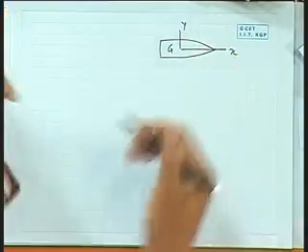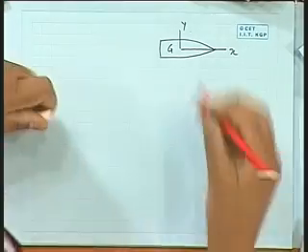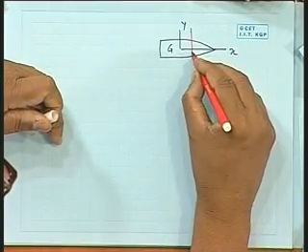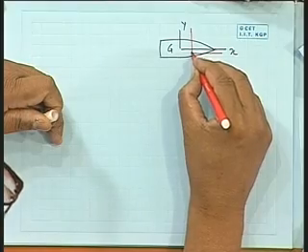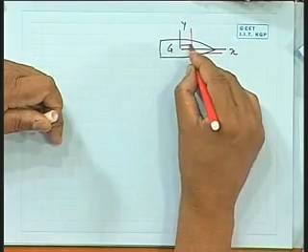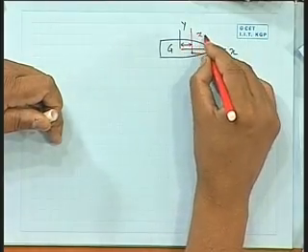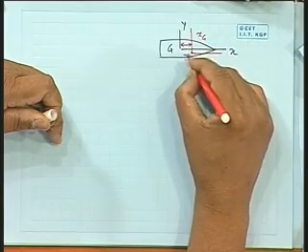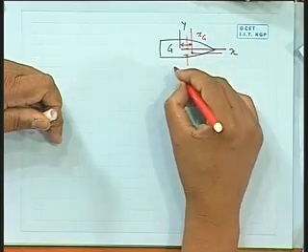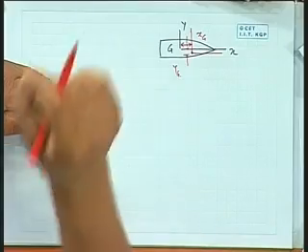But if I took an axis in a general sense somewhere else as the coordinate axis, so that this is my xg and yg, in other words the body coordinate system is somewhere else and the center of gravity has coordinates xg, yg. You can say the center of gravity is, say, 5 meters forward of midship, if I took midship as the origin.